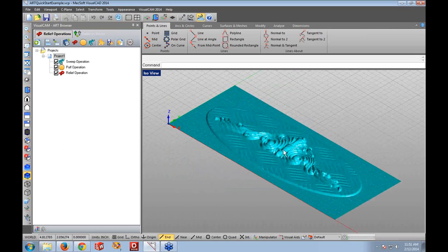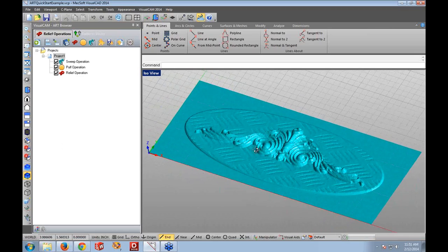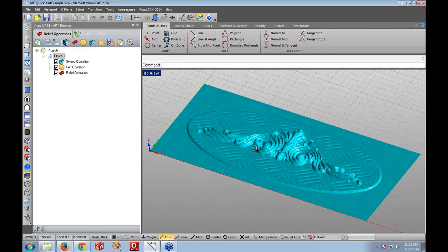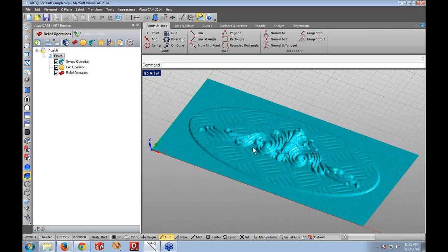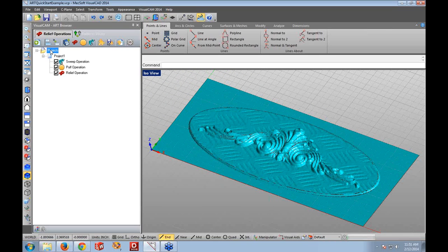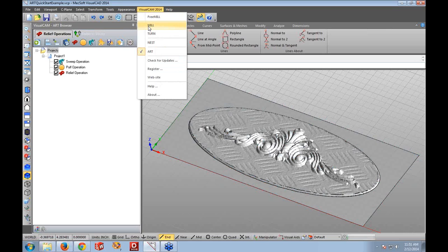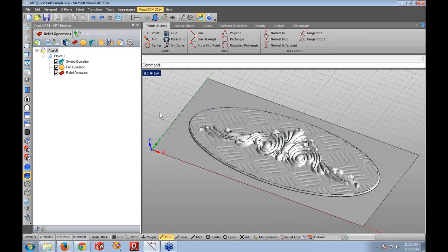Now this artwork is ready for your downstream application. You can use it for milling applications, or you can save it out as an STL if you'd like to send it to a printing application. I'm going to quickly hit Export Meshes as CAD. This will convert it to data, a polygon mesh, which can then be used in your milling application. If you'd like to use VisualMILL to generate toolpaths, I have it exported, and I can quickly switch over to the milling browser and generate some toolpaths on it.